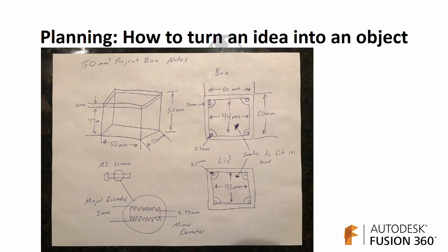Or in another part like the lid, you want to make sure that the screw goes through it with little to no resistance. So you're not threading it into the lid and threading it into the part and maybe not getting things to square up and line up the way you want. So you've got to think about how big the screw is as far as its diameter, and then how big a hole you want to use so that it can actually self-tap into it.